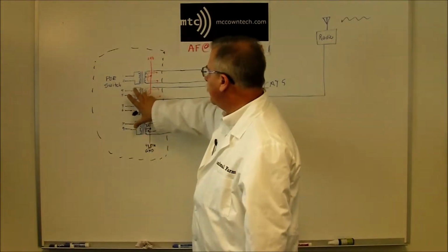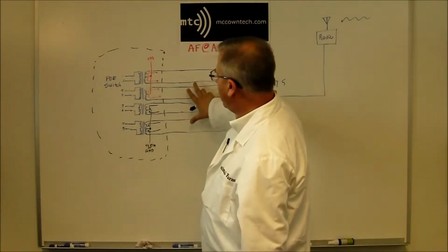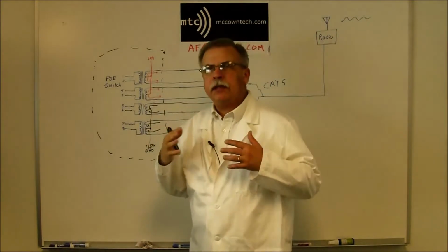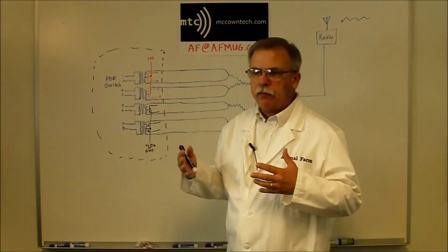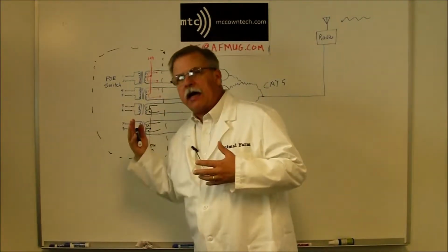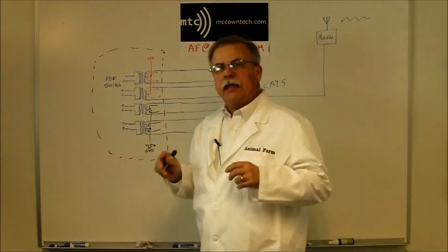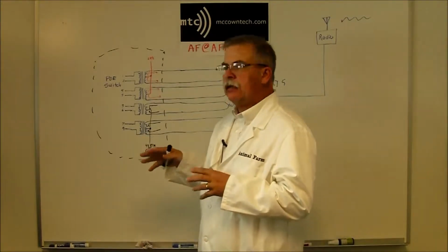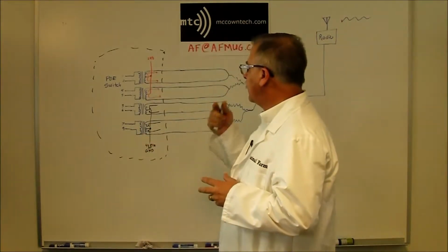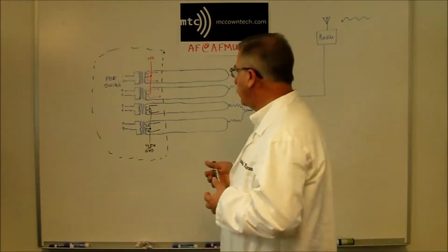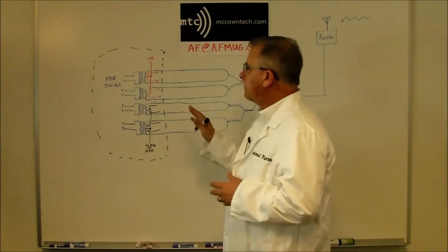Coupling that through the transformer into a real-world line impedance of the Cat5 cable also provides what they call galvanic isolation, so impulses on the line don't get into the chip, not nearly as easily as if it was directly connected. Electrostatic discharge resistance, lots of reasons for using the transformer.